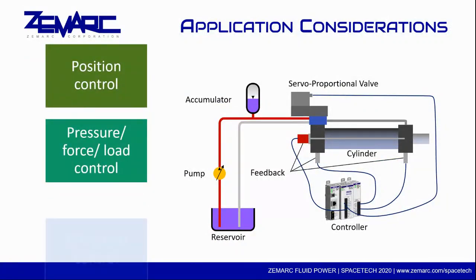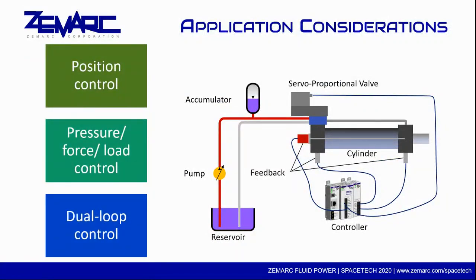Delta RMCs are best used for fluid power systems that require closed-loop control of either position, or pressure and force, or seamlessly transitioning between the two modes. Dual-loop control ensures that users can precisely position an actuator without exceeding a desired force limit, or exert pressure on a workpiece while avoiding an over-travel situation which might damage a part or the system.